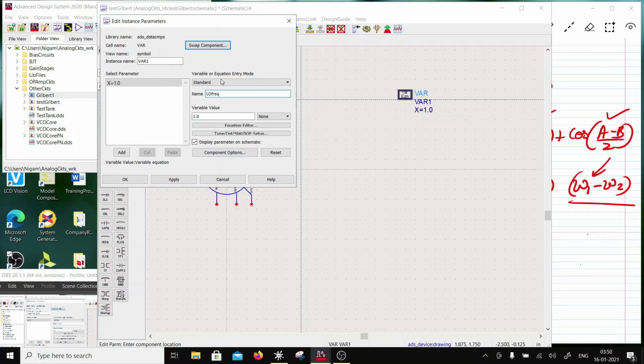So I am going to have this LO FREQ as 2.4, pure number, correct? Apply. Then I'm going to have the IF FREQ. This is around 11 megahertz, right? So 0.011. I'm considering I'm giving a Wi-Fi baseband input, right?